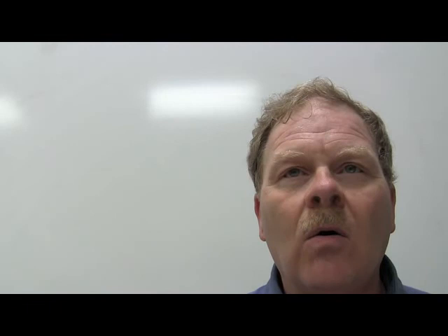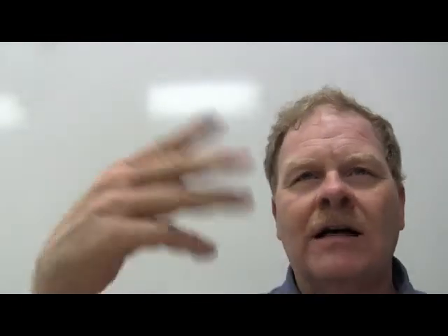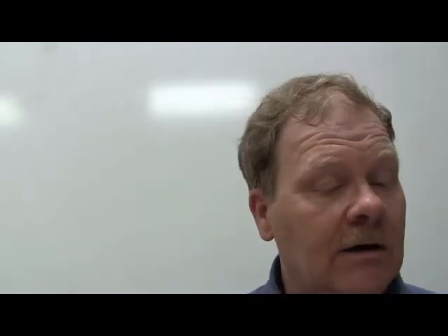Now let me ask you this. Why would you check the ground connection if it's drawing more current? If it's running too slow and it's not doing it right, your ground connection could be a bad connection and cause it not to run. But a ground connection is not going to cause it to draw more current. It can cause it to draw less and not work right.